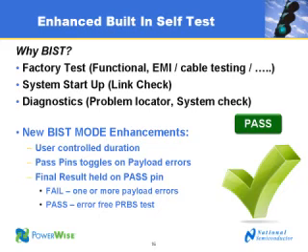So one of the results of this enhanced built-in self-test is now designers can look at it not just during the development and prototype stage, but actually use the BIST during operation of the system. And that's because the user controls the duration, and the pass pin can toggle on payload errors. And then finally, the final results are held on a pass pin. So if it's fail, that means you encountered one or more payload errors. And if you pass, that means you're error-free on the PRBS test.